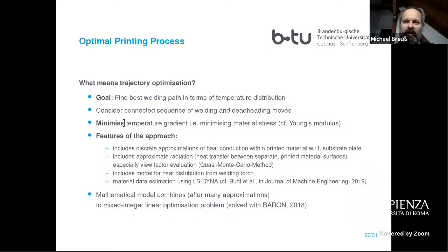And when it comes to the view factors, things get again a bit delicate because you have to take into account the local geometry and so on. And when you really want to boil it down to something that you can compute, simple models that you find in the literature amount to evaluating numerically a higher dimensional integral. In our case, in our model, it's 4-dimensional. I guess this will be standard in these geometrical configurations.